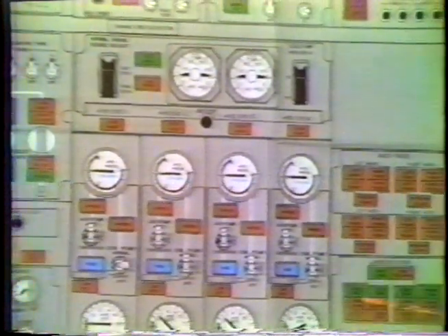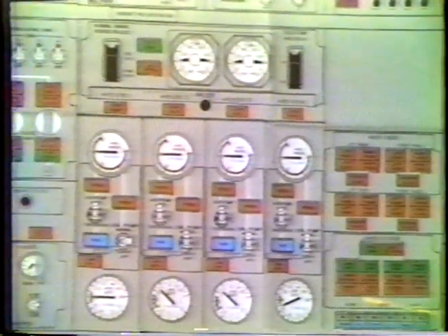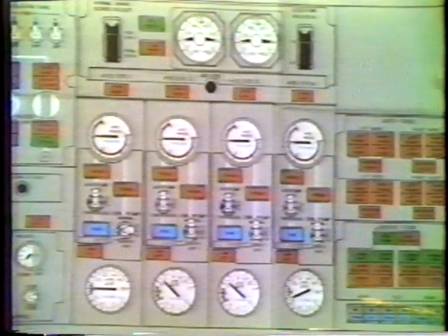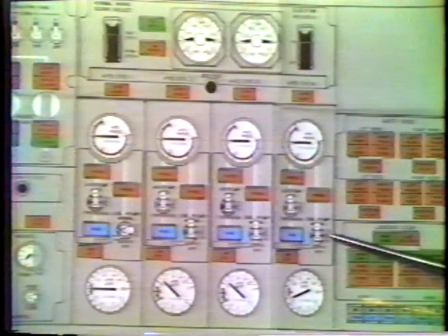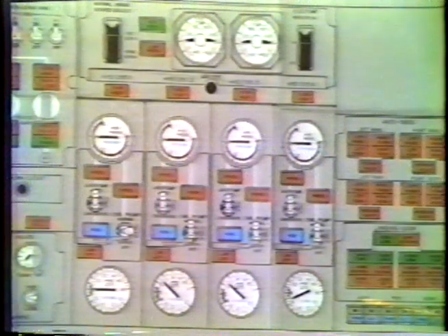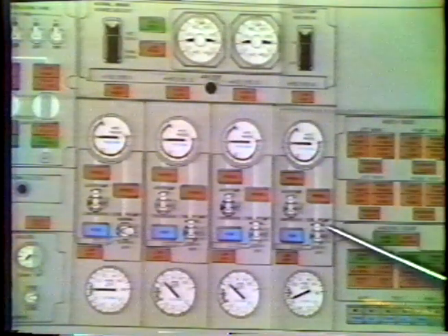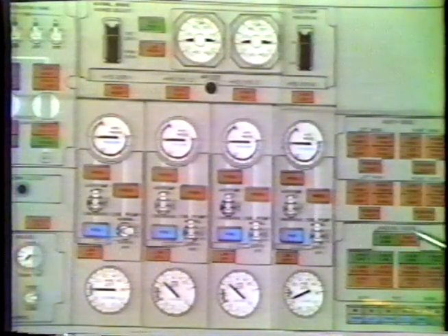Since the engine pump is running anytime the engine is running, that would show up as an engine pump problem if the air pump was turned off and the engine pump was depressurized and the temperature didn't come down, because the only thing operating now is the case drain for the engine temperature. And since it won't come down, that's the problem.